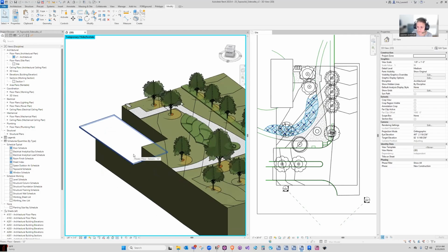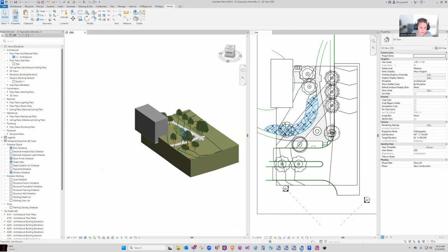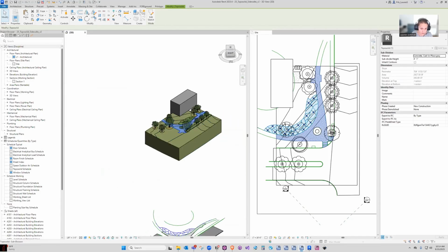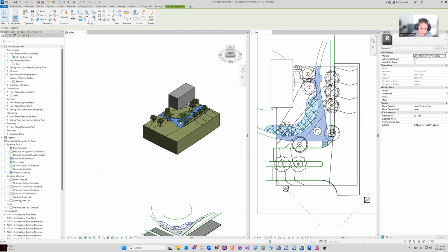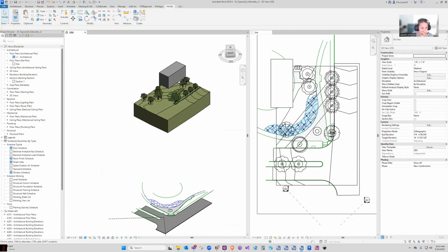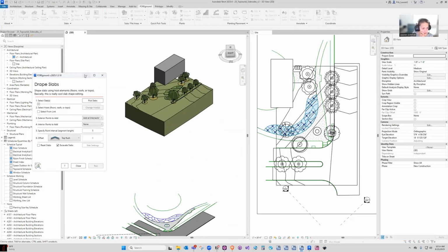The other main way that you can use excavate, and it does the same functionality, but I think of it as a different use case, is you can use excavate to essentially drape and then excavate your object. So I have a subdivision up here as a sidewalk. I'll go ahead and just delete this for now. And I'm going to drape this one that I have down here just to show what that looks like. So I'm going to use foreground to do this because drape is a foreground functionality.